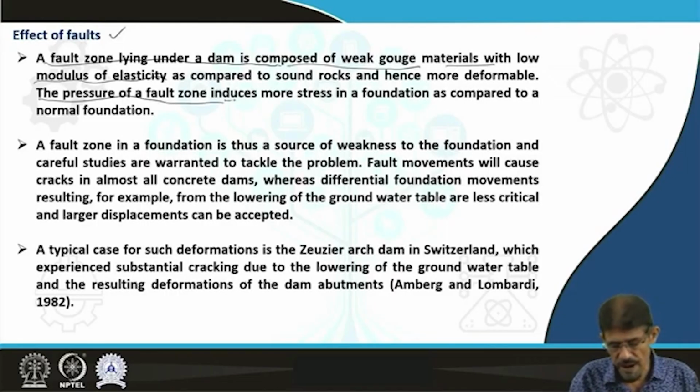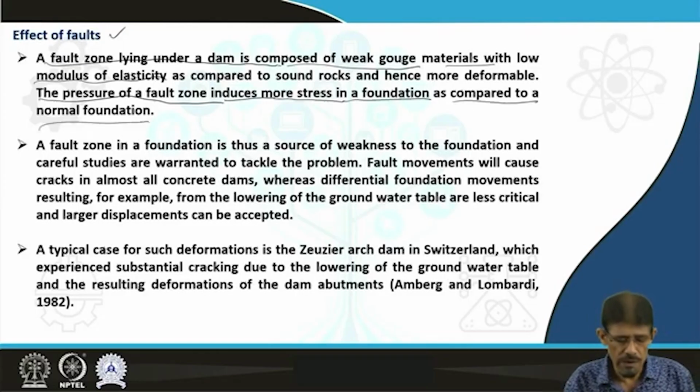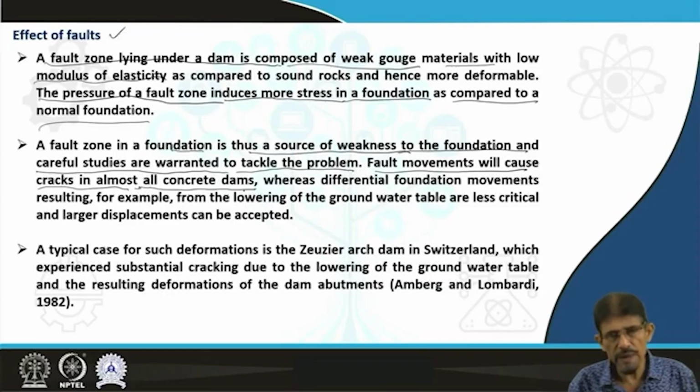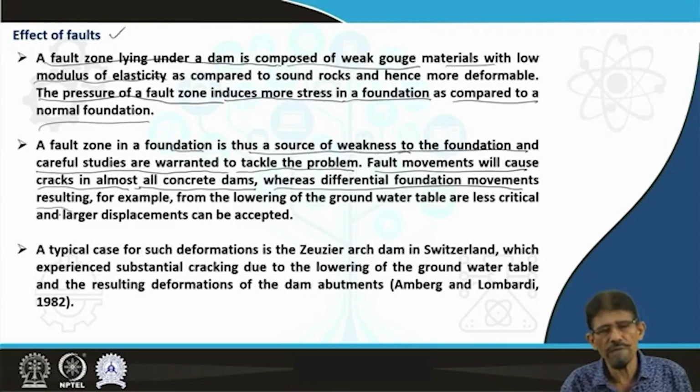Therefore, the presence of a fault zone induces more stresses in the foundation as compared to the normal situation. A fault in the foundation is thus a source of weakness to the foundation and creates a lot of problems related to seepage, percolation and loss of strength. Careful studies are warranted to tackle this problem, and fault movement will cause cracks in almost all concrete dams, whereas differential foundation movement results due to the presence of weak material associated with the fault zone.